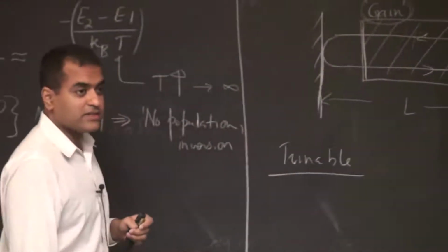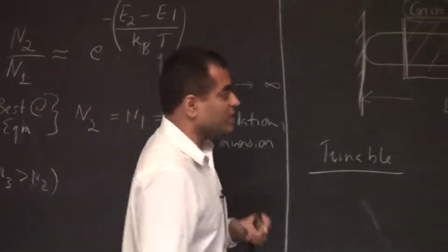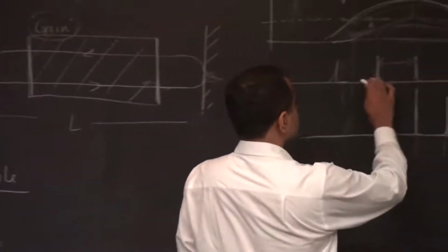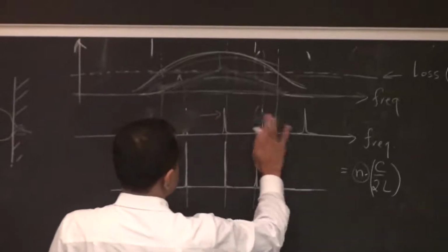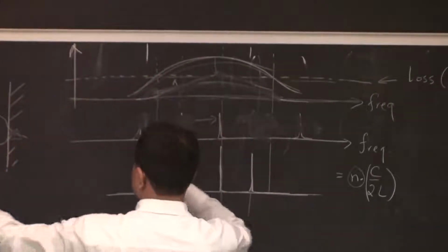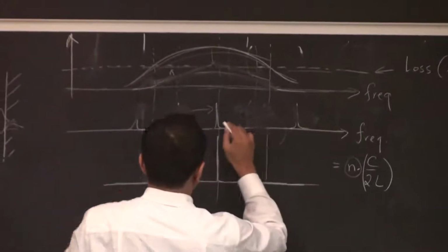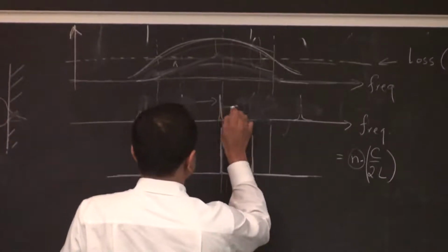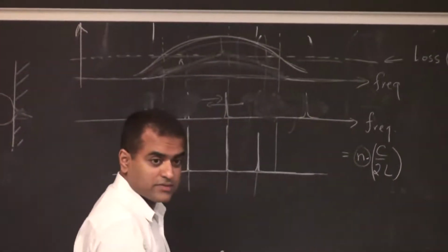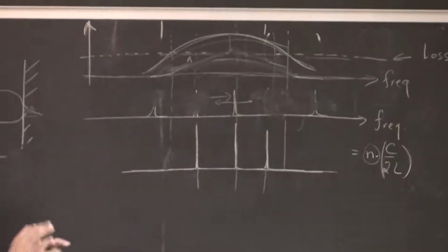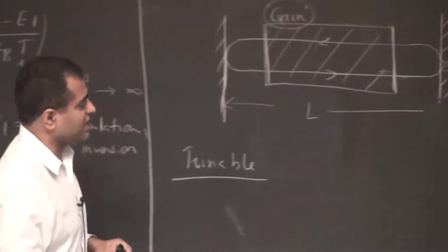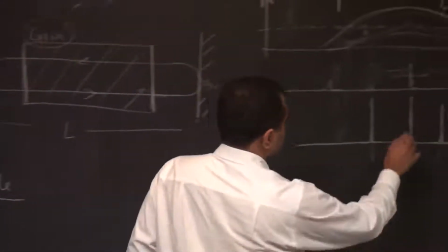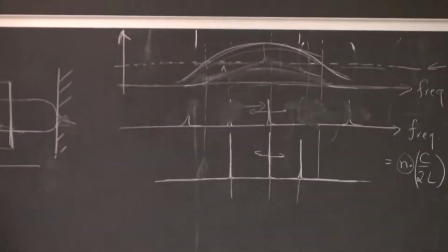A tunable laser. So you have selected one frequency. Let's say you have somehow pushed out all these modes because of the length of the cavity. But now you still change it, and this thing is going to move around. Right? It's going to move around because it's still responding to the change in the cavity length. And therefore, this is a very nice way to also make it tunable.